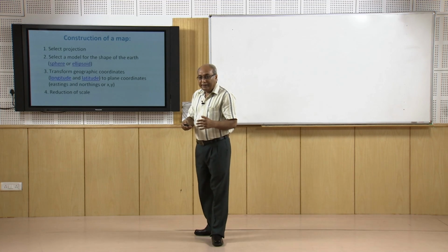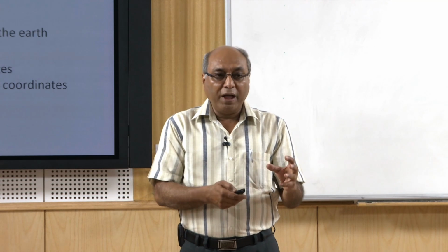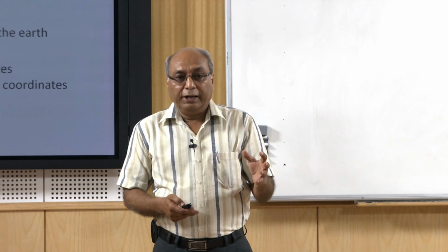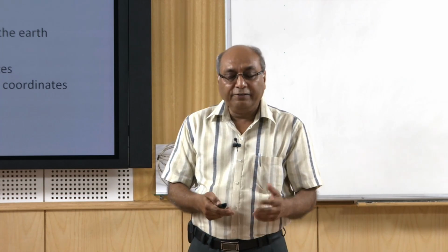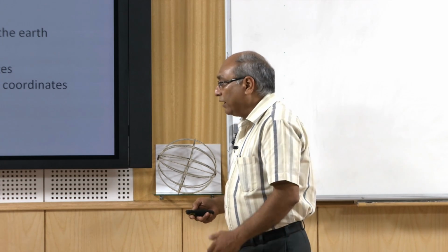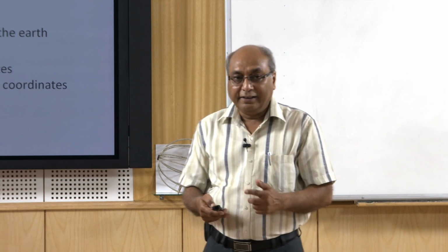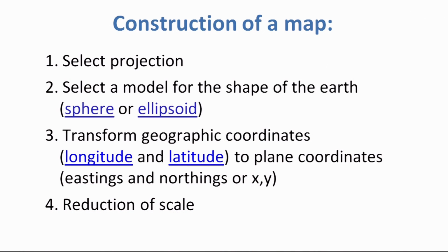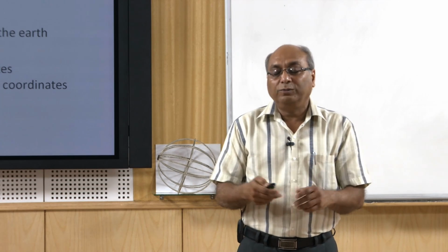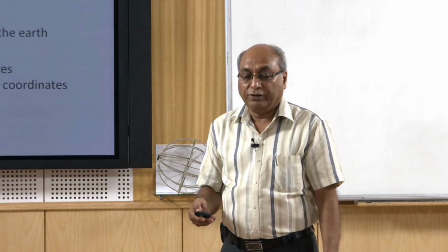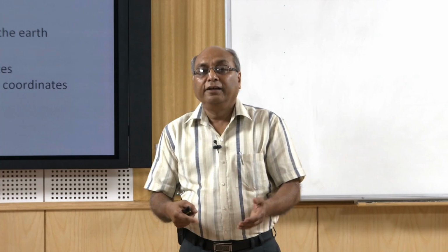The best part here is that using computer programs or GIS software, we can change our data, our maps, from one projection to another quite easily. It is very easy to change projection with vector data, but it is relatively a little difficult with raster data, but nonetheless the projections can be changed. Another thing is that whenever we change the scale, projection issues might also come up, because if you go for smaller scale maps that cover a large area, then the curvature of the earth will come in, and therefore an appropriate projection has to be chosen, because the main aim here is that the shape of a country should not change, because if it changes, then the area of that country will also change.